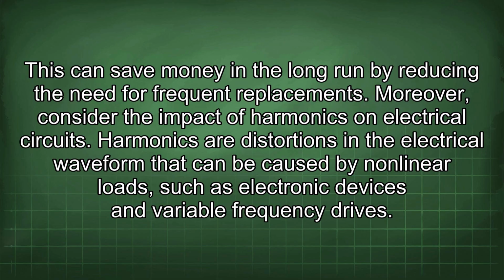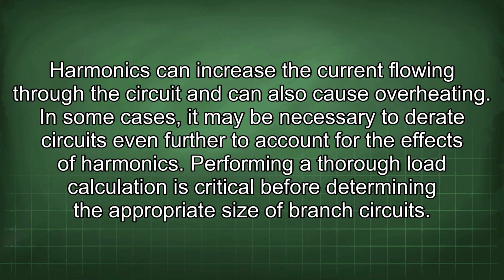Moreover, consider the impact of harmonics on electrical circuits. Harmonics are distortions in the electrical waveform that can be caused by nonlinear loads such as electronic devices and variable frequency drives. Harmonics can increase the current flowing through the circuit and can also cause overheating. In some cases, it may be necessary to derate circuits even further to account for the effects of harmonics.